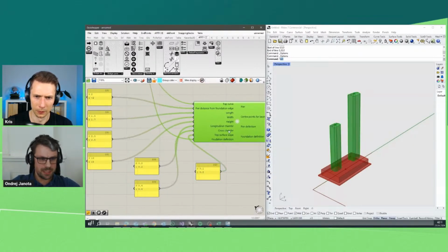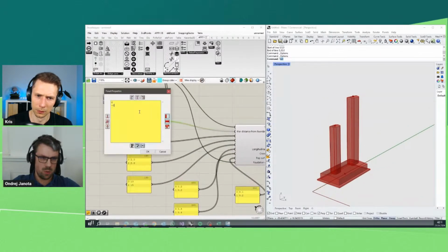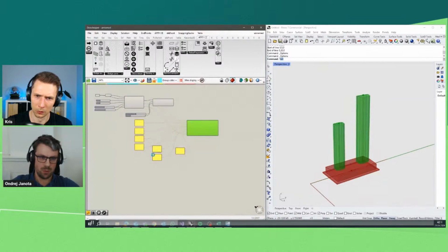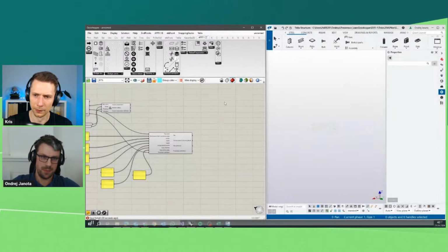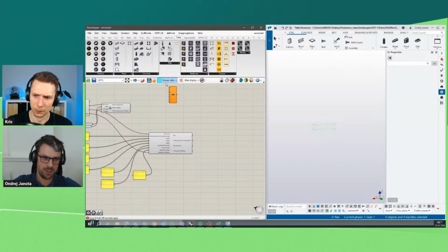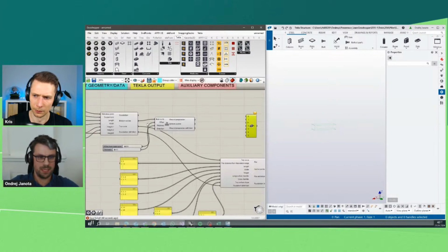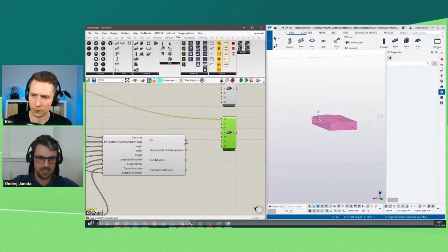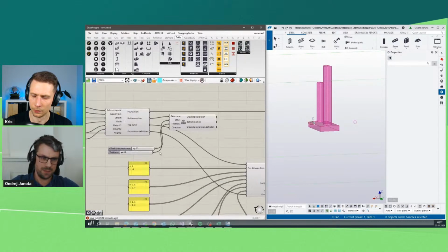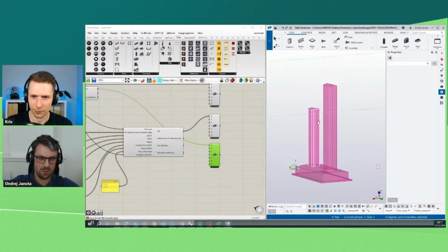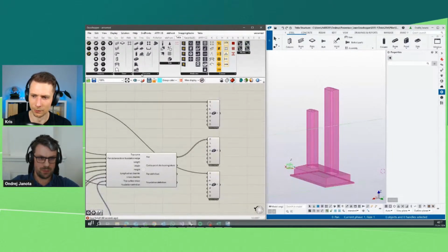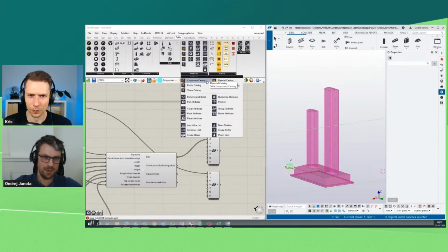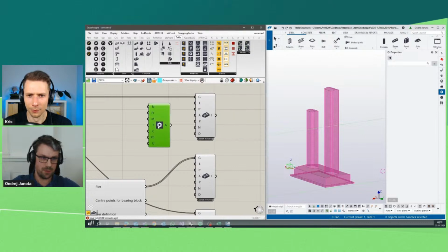Well, what is maybe a little bit unclear here is where is the reinforcement right now. It is not shown in Grasshopper, but we create our own C# class, which bears the geometry together with the reinforcement geometry, and we, let's say, unwrap that class at some point. To do so, you need to know a little bit of coding, but again, I think you can overcome this with the default workflows in Grasshopper. It will probably create a little bit bigger monster spaghetti, but still it's okay, it's workable.